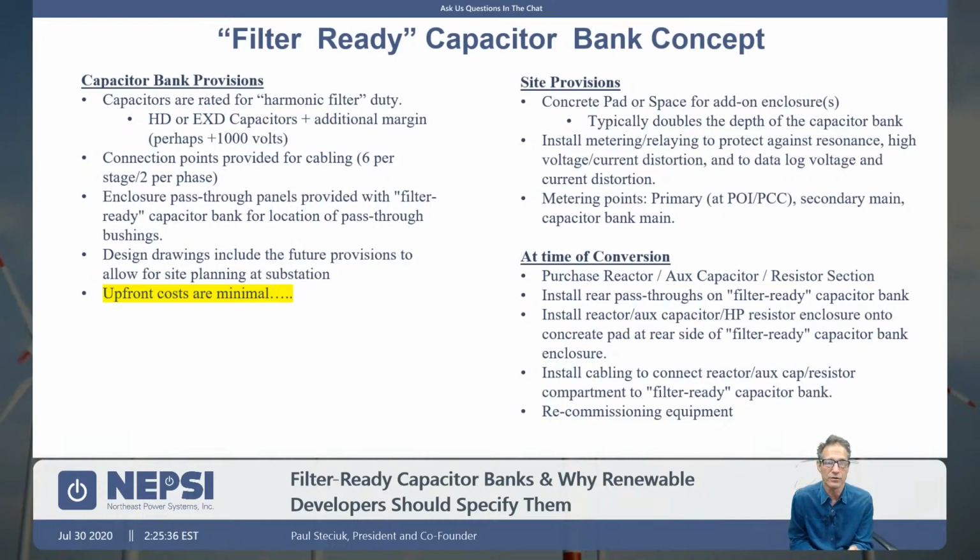It should be something like a Schweitzer 735 power quality meter, an advanced power quality meter, something that can measure and log harmonics. Install that in the capacitor bank feeder cable somewhere in the feeder breaker area, and also install it on the main breaker of the plant, the main secondary breaker and the main primary breaker, so both sides of the transformer.